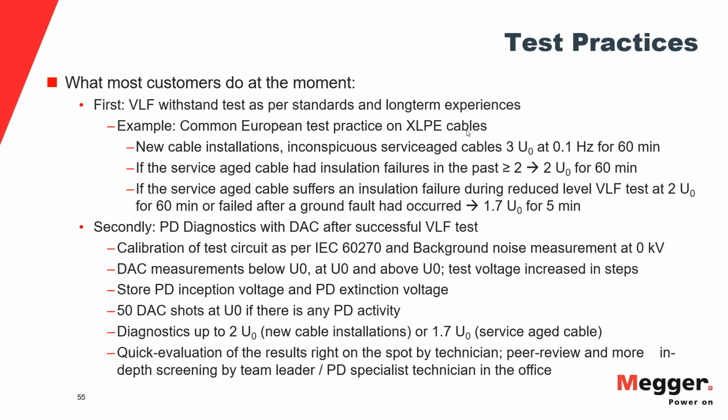Now, this changes when you look at service-aged cables. Some of the feedback I got was that if the service-aged cables already had a certain number of failures, for instance 2 or more, they would take down the magnitude of the test voltage, but they would not compromise on the time, because electrical trees need time to actually produce that flashover under VLF stress.